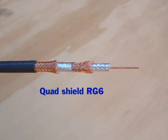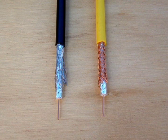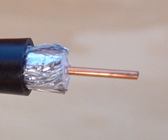For maximum ingress protection, make sure you use either tri or quad shield RG6. And check the quality of the shields of the cable. There's a big difference in shield types and coverage between manufacturers. Another important specification is the DC resistance of the center conductor and shield. Very important when the cable is used to supply power to attached devices such as cameras and satellite antennas.